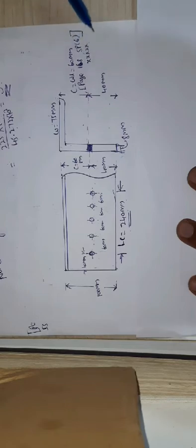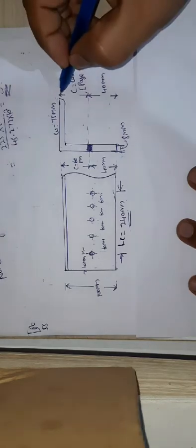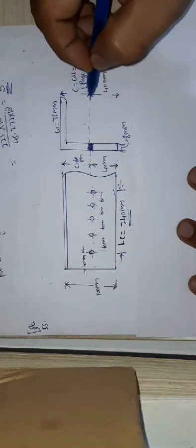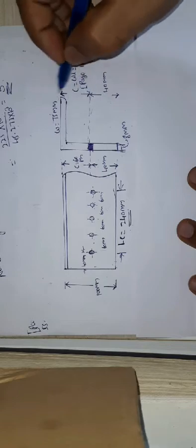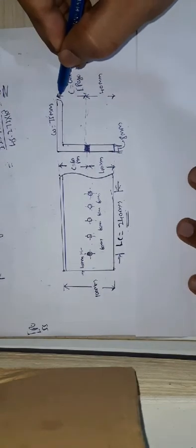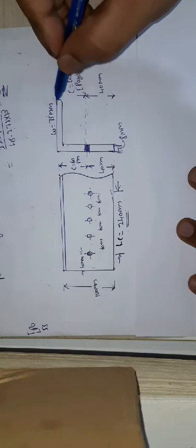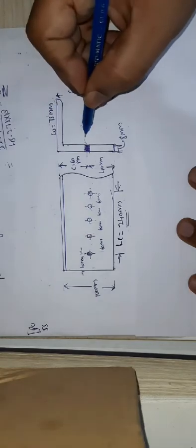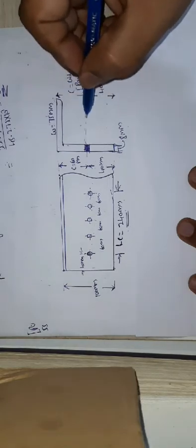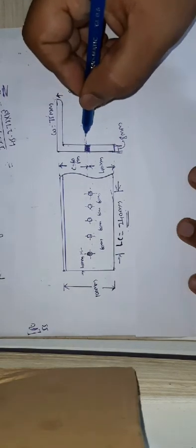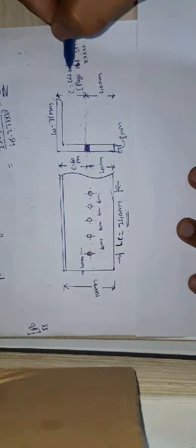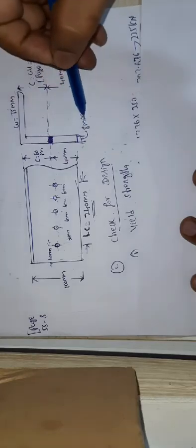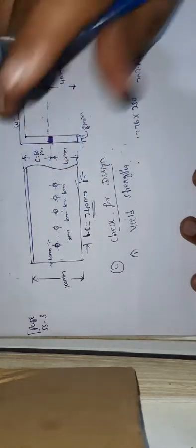In the steel design handbook, we take the distance between the top of the connecting leg to the point where the bolt line is provided. So here the bolt line is provided, and that is C or WL, taken as 60 mm. Here that is given, and the thickness will be 8 mm. This is the pictorial representation of the connection.